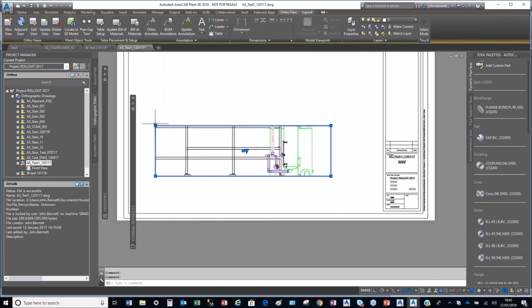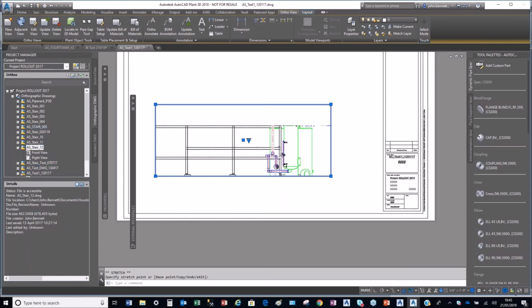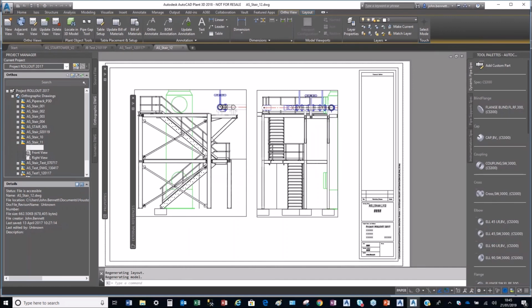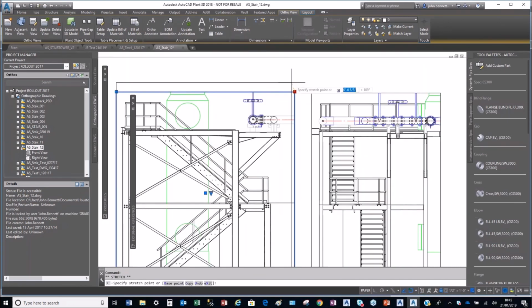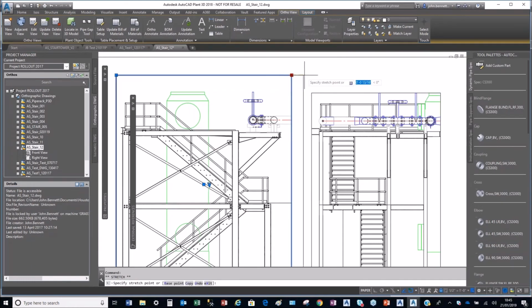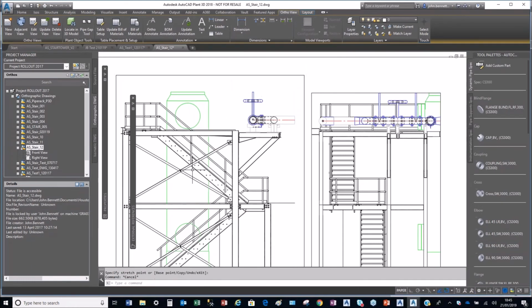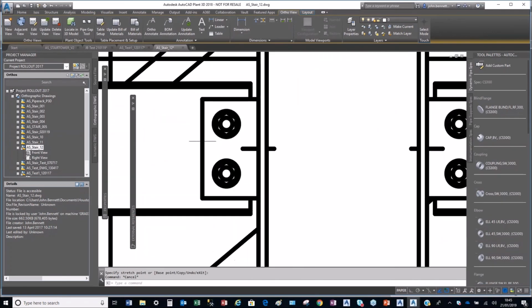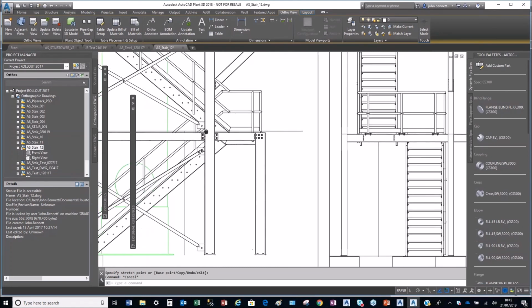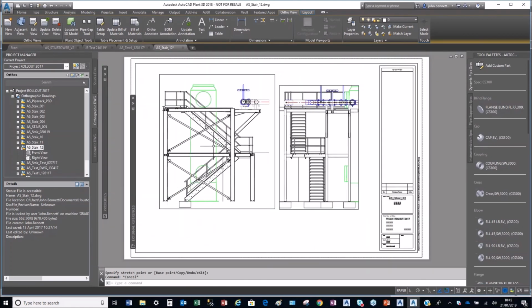So depending on what the view is, you can adjust it in here. And this is one of a stair, I think, here. We've done this before, so I can open that there. And obviously these are adjustable inside Plant. So depending on what you want to do, you can adjust it to see things. And the point I'm trying to show here is you can actually get quite a high level of detail by combining the models back together, back into the plant environment.